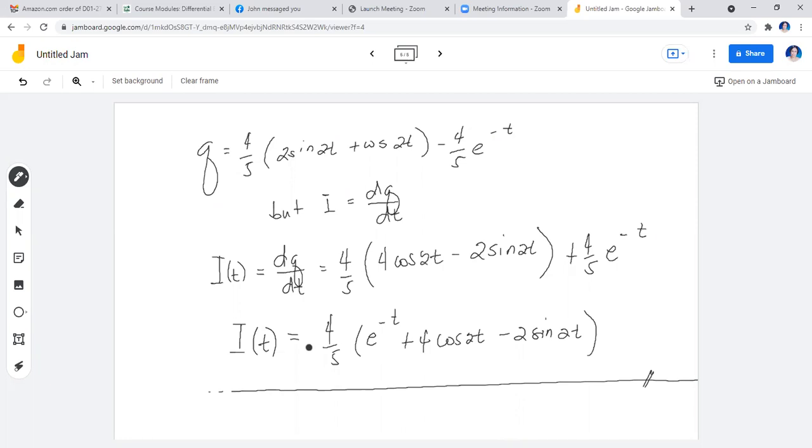Whenever you solve problems like this, class, before I forget to mention it, although it should be fundamental knowledge, your calculator should be in radian mode. Why? Because when you multiply the 2 in here to the time value given in the problem, the argument of your cosine, the same with the argument of your sine here, will be in radians. They are not degrees. So your calculator has to be in radian mode. Also make sure that the time unit you have in here is seconds. So far, this is the answer to our fourth sample problem on the RC circuit.